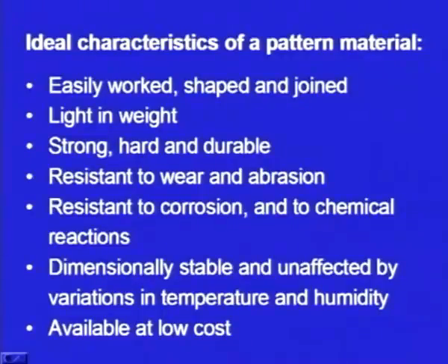And next one, it should be dimensionally stable and unaffected by the variations in temperature and humidity. When we use metallic patterns or alloy patterns, there is a chance that they may expand if the temperature in the shop floor is high.